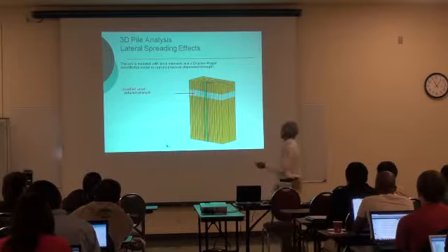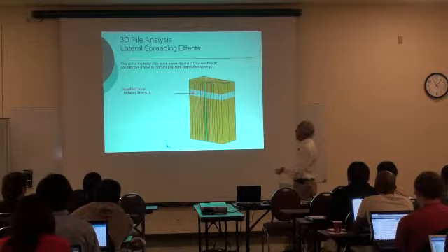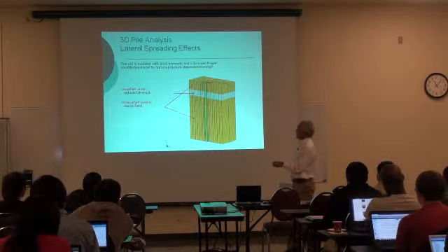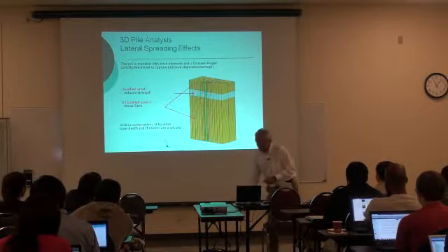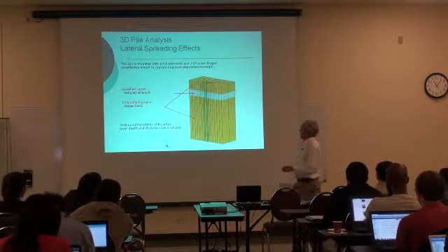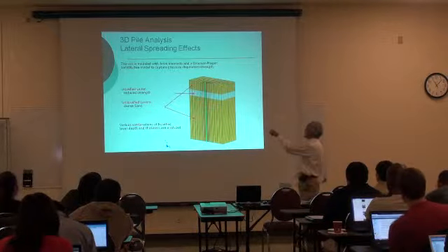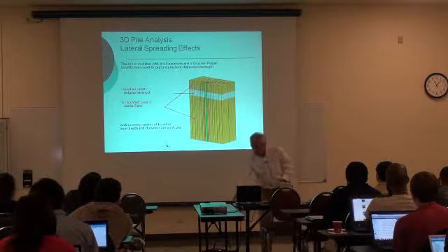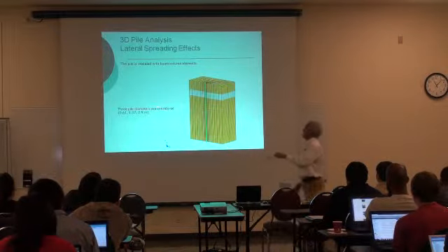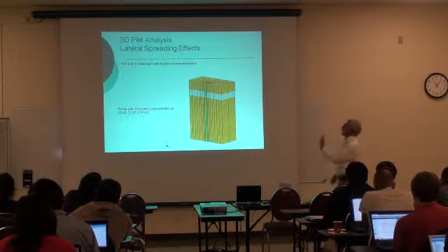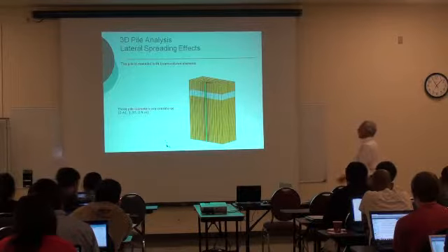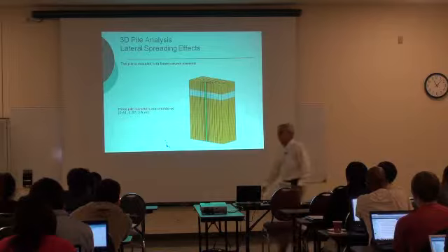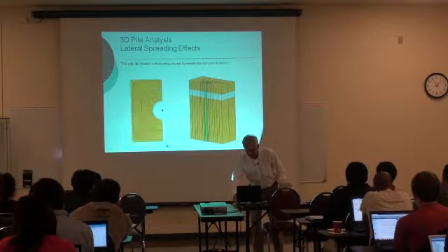So we use a liquefiable layer using a reduced strength. We use unliquefied layers using dense sand characteristics. We use different combinations of thickness of the liquefiable layer and also the position. And also we use different pile diameters, 0.6, 1.37, 2.5. We use the displacement beam element. We use fiber sections to account for the nonlinearity of the pile, and so forth.